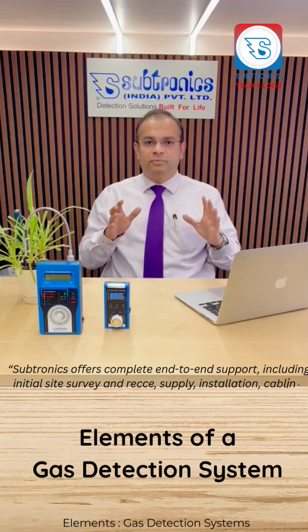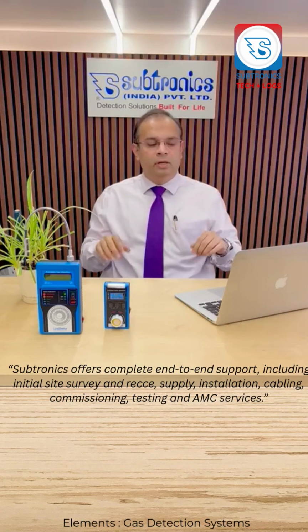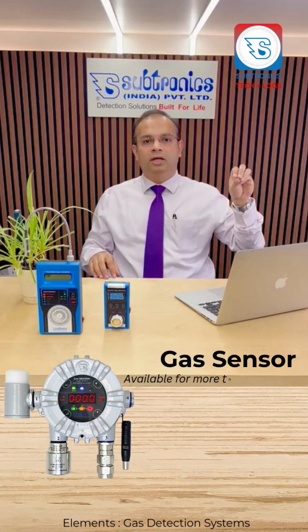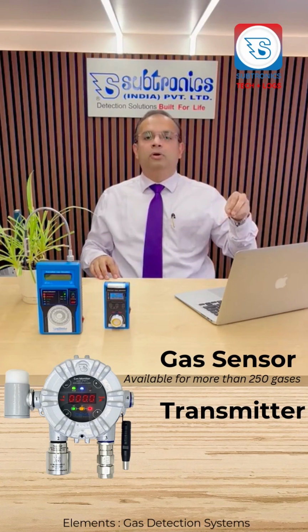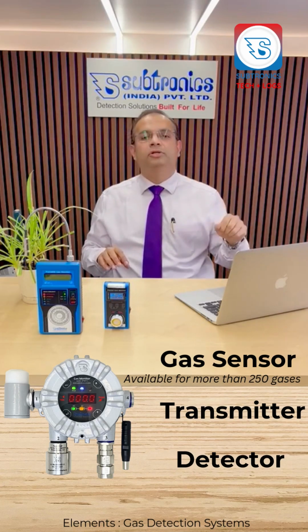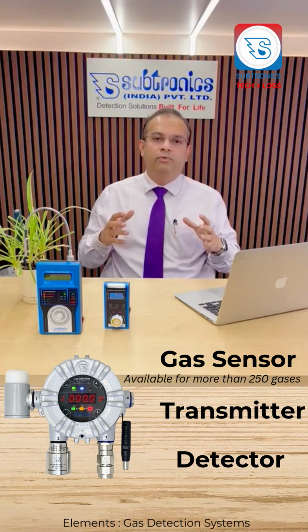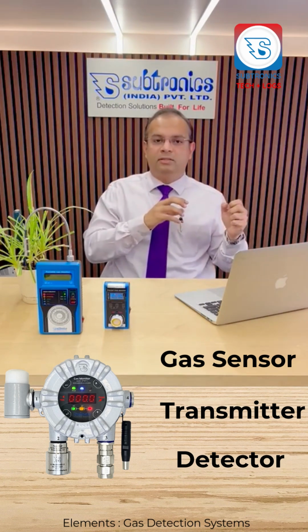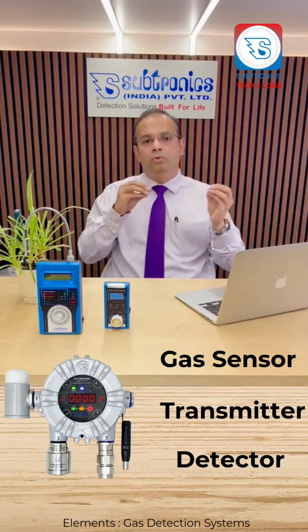Any gas detection system has basically got three elements. The first one is the gas sensor. In the industry, it's also called the transmitter, or the detector. This is the main device which is continuously trying to sniff the air for the kind of gases that we are going to detect. The sensor readings are then taken to a control unit.